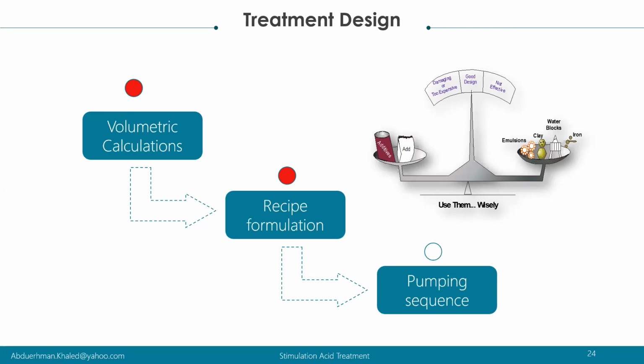Another additive is a corrosion inhibitor intensifier. In some cases where the temperature is higher than 250 Fahrenheit, usually the corrosion inhibitor by itself is not enough. Why? Because the temperature is high, and it needs assistance from other chemicals to enhance the corrosion performance. In fact, there are two types of intensifier. They are formic acid and potassium iodide.